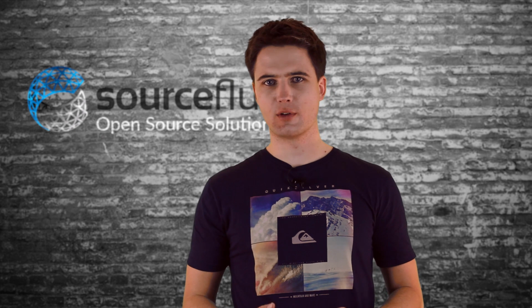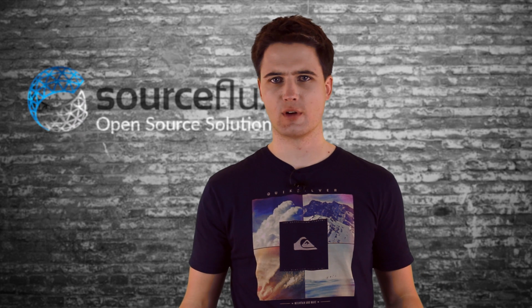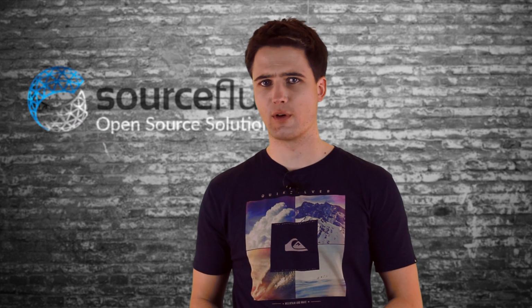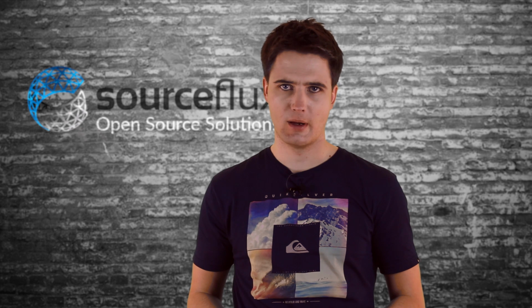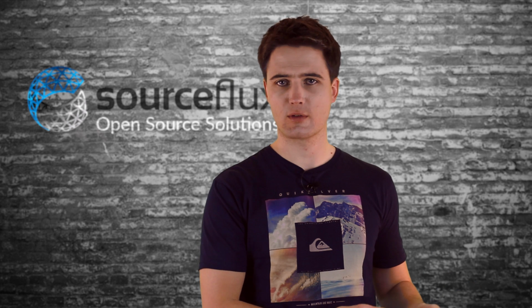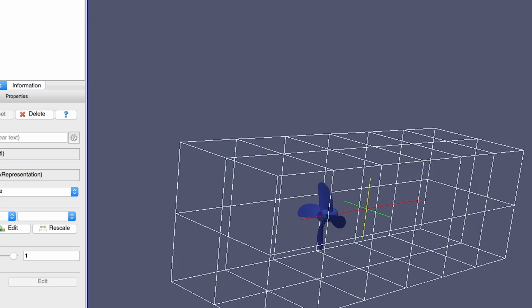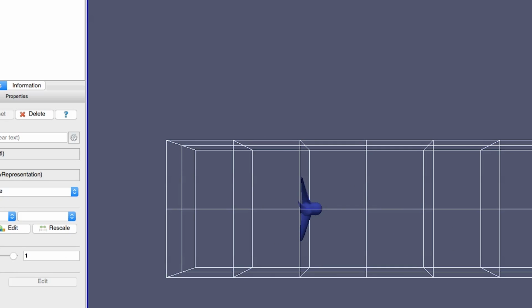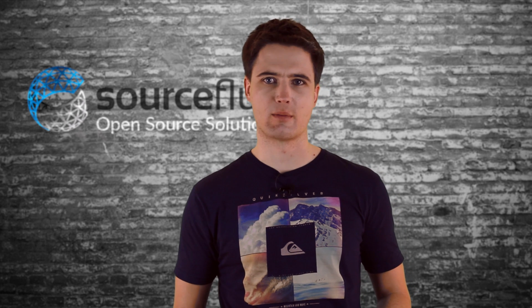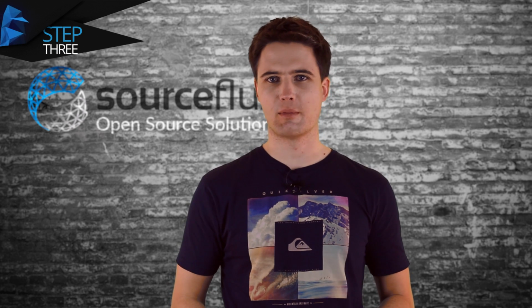Once both the geometry and the background mesh have been loaded into ParaView, I'm assigning different surface representations to both of them. I'm using surface with edges for the geometry, which is in this case the propeller, and for the background mesh I'm either using the bounding box representation or the wireframe representation. In this case we haven't made any mistakes. The propeller geometry is aligned perfectly inside the background mesh, and we can proceed with the snappyHexMesh tutorial, which takes us to step 3, setting up the snappyHexMeshDict.